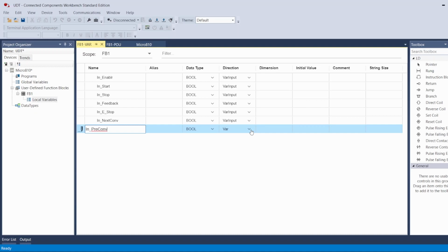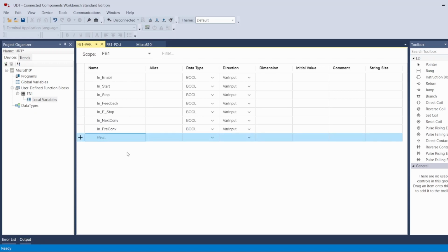how, if you have a block already set up and there is a tag that you don't need but you don't want to delete it, or for example, you want to create a user-defined general block to work in every situation and then you bypass whatever you want to. So let's add it, and I'll show you how we can deal with it since we're not monitoring the previous conveyor. And then also here we will need the outputs now.